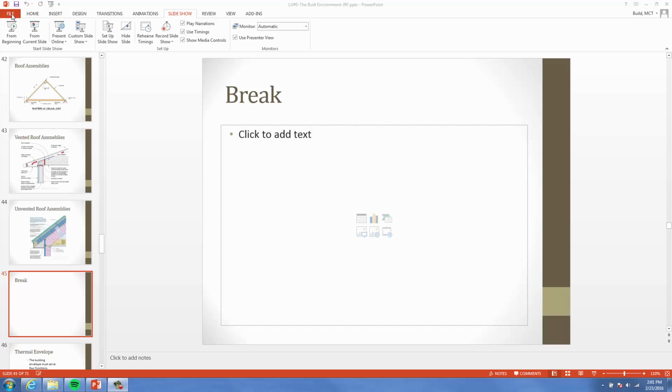What are they going to wrap it in after that? Are they just using like a metal siding? That's a good question. I don't know. I think they're doing some stucco on it, but I don't know the answer to that. Maybe they'll have siding on it by the time we get there. The other part of it too is you've got a heavy steel structure that is the structure of that building, and then you've got light gauge steel that's framing up that curtain wall. That makes the thermal break. That cuts the steel off from being exposed to the outside to cut down on the conductivity.